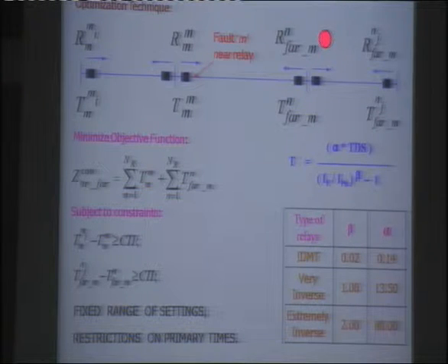Now you may ask, or anybody may visualize, how it can be made possible that the same relay will act faster and the same relay will act slightly delayed in such fashion by the same setting. It is because the nearer the fault is to a location, the more the fault current will be at that location, and the fault current will reduce substantially as it moves away from the location of the fault. So when it acts as backup relay, the value of the fault current sensed by that relay will be smaller.